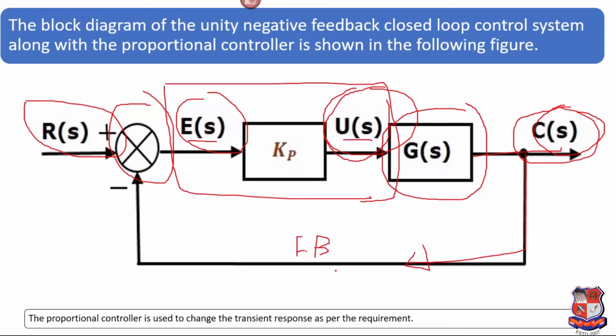If we take one example, suppose this one is my whole process, in which we want 50% output after this process. Whenever we provide some amount of reference signal, the raw material, we can produce an amount, but ultimately we are not achieving the 50%, we are just achieving 45%. So with the feedback, we are generating only 45%, but we have to achieve 50%. So 5% is our difference, which is the error.